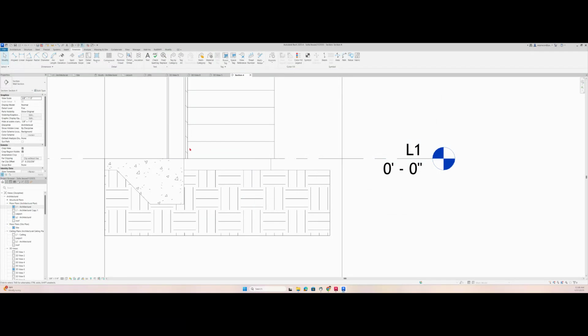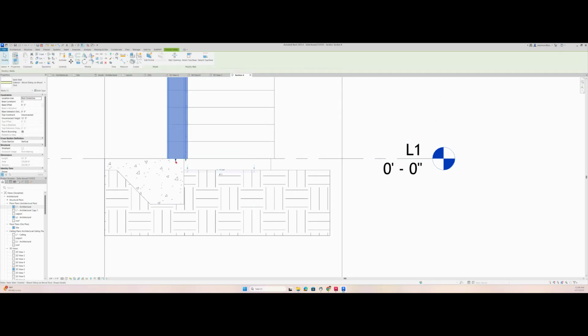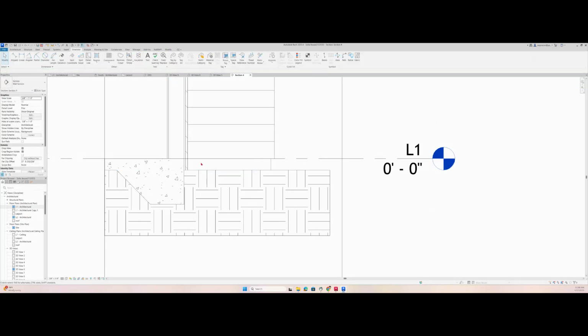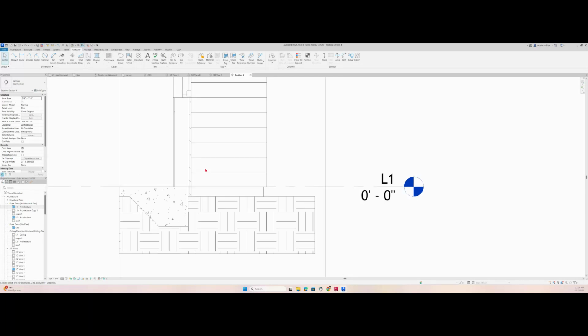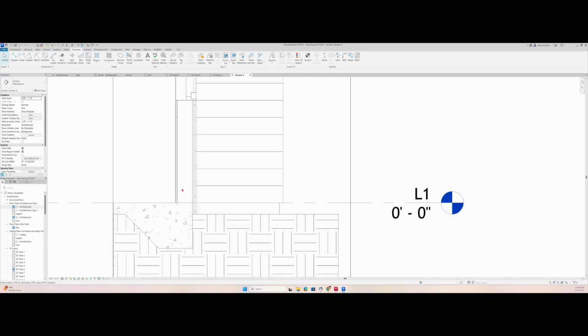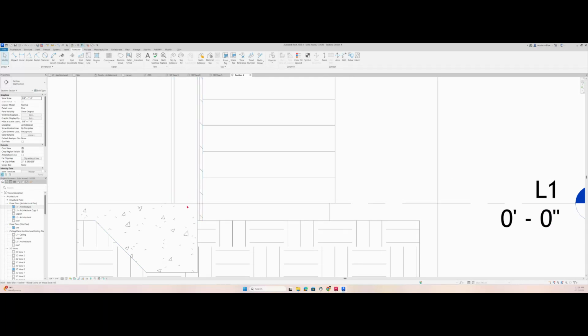And here, guys, on this wall, you're going to see those two little arrows, so you can pull the siding down a little bit, so the water doesn't penetrate, right? Of course, here is going to be a sidewalk or a little bit below, right? But let's keep going with the little detailing, okay? So now here we can put an anchor bolt, we can put a wood blocking, right?